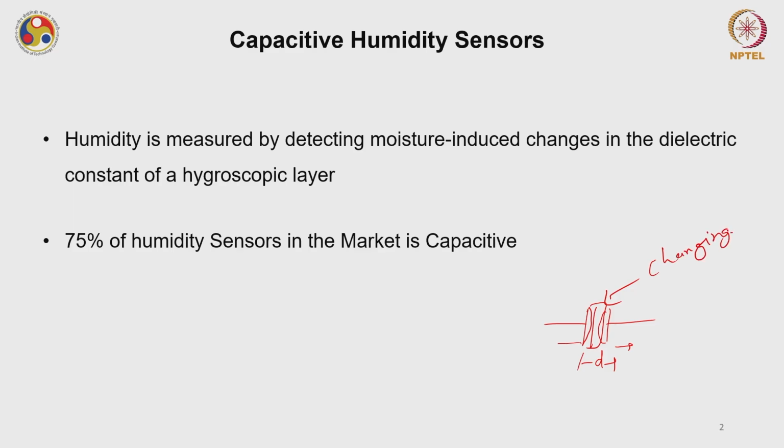So, if the dielectric property of this material is changing with respect to something, I can use this simple parallel plate capacitor to detect that non-electrical stimulus.